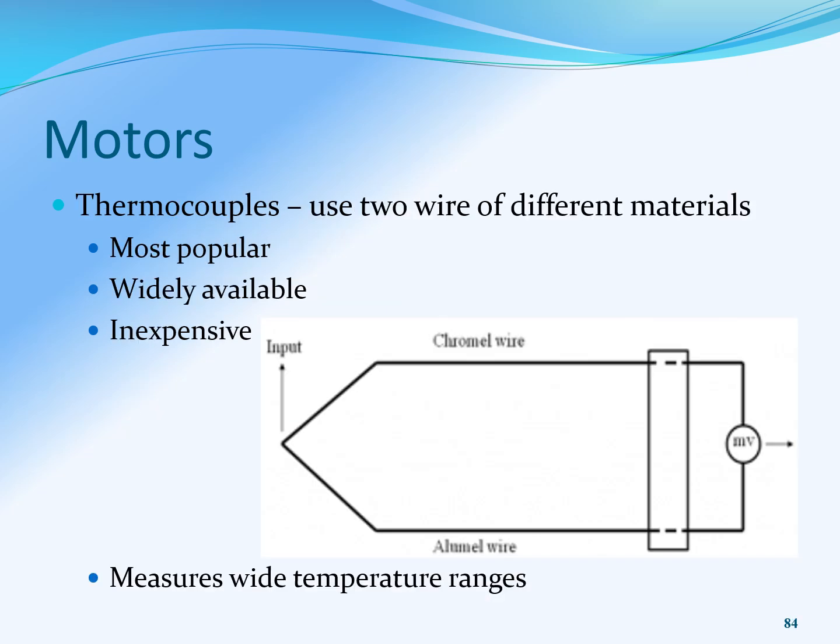You've got that thermal overload relay that will measure the temperature of the motor and then provide that feedback. Once it reaches a certain temperature, like I said, it will cut out. These are typically the most popular because they are so inexpensive and widely available. It doesn't require a whole lot of parts to operate. A lot of times you're going to find that your motor has some kind of thermocouple to prevent any damage to the motor, or protect the motor, if you will.